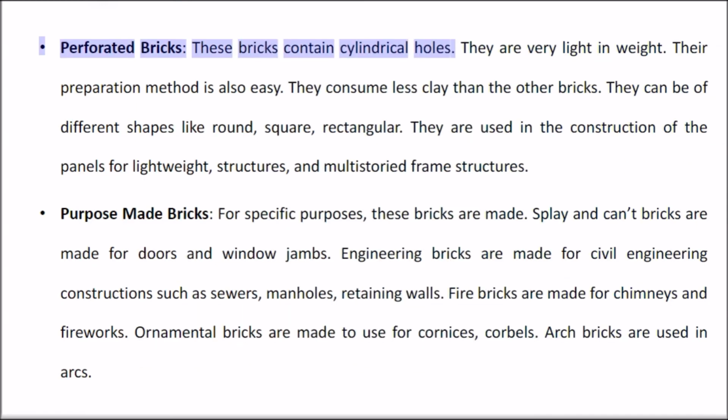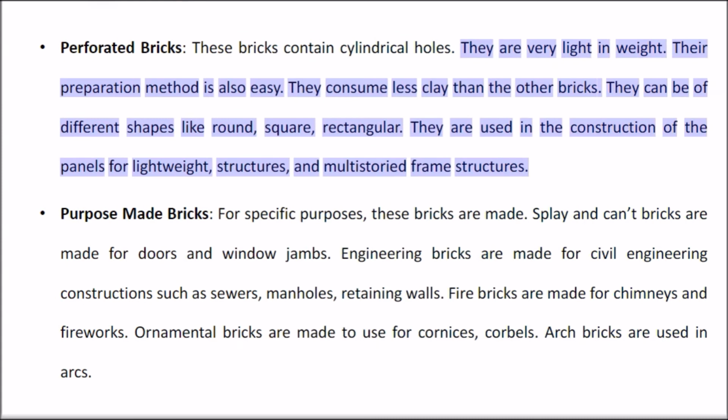Perforated bricks. These bricks contain cylindrical holes. They are very light in weight. Their preparation method is also easy. They consume less clay than the other bricks. They can be of different shapes like round, square, rectangular. They are used in the construction of the panels for lightweight structures and multi-storied frame structures.